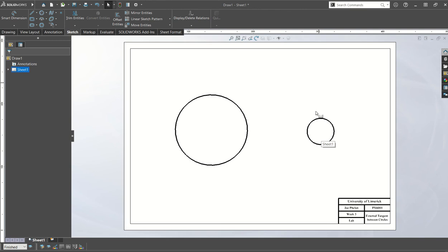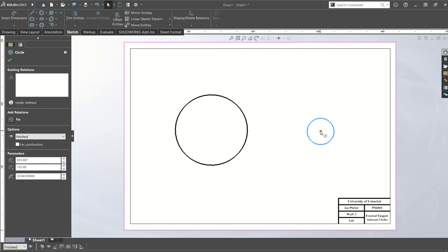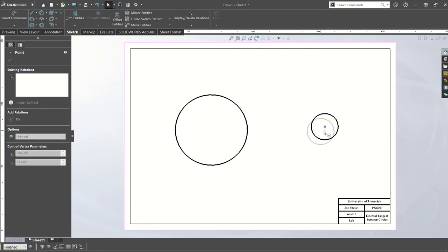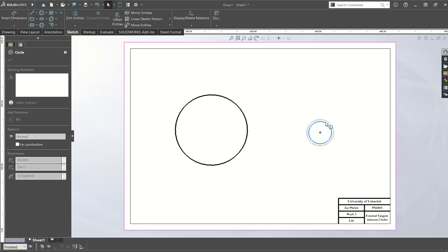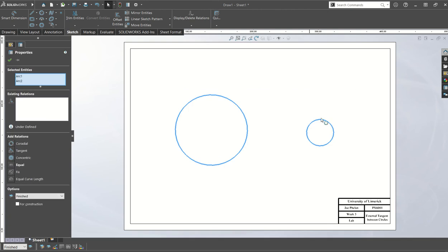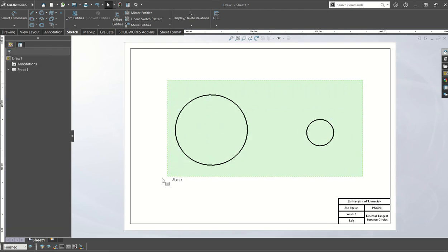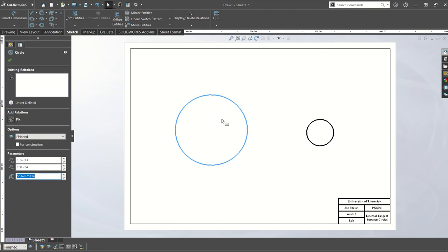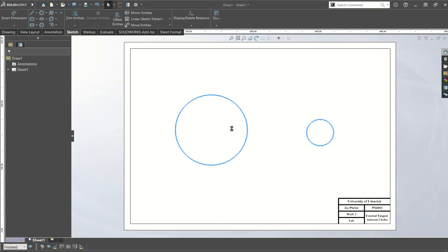If you have it a bit bigger or a bit smaller, it just changes the nature of how you interact with the problem. Now, with the way that I've drawn it so far, these two circles are free to move around, but they're also free to change in diameter and radius. So if I select those two circles, dragging from right to left and just hit off those circles, it selects them.